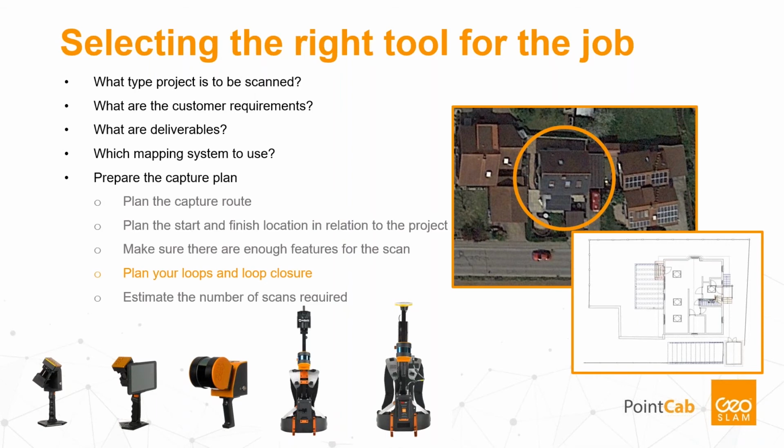Nevertheless, things to consider before the scan is the capture route preparation, if possible, knowing the place where you can start a system and make sure there are enough features in the environment. For each ZEB system, a loop closure is required. Some bigger projects than 20 or 25 minute captures might also require to split the surveys into several scans. And in general, a short project planning in the office can help to save time on site.